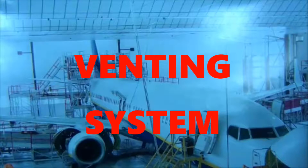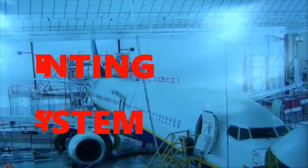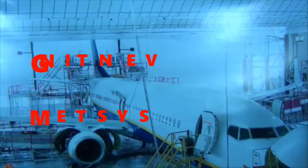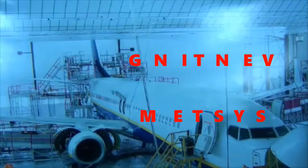So there has to be an equalization with the pressure on the outside of those tanks, or the atmospheric pressure. So we have a venting system, allowing venting to the atmosphere through the vent tanks. The vent tanks are located on the outer ends of the wings, and you have those there for that purpose.